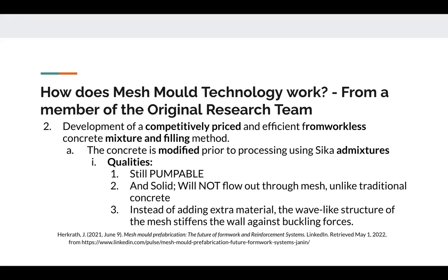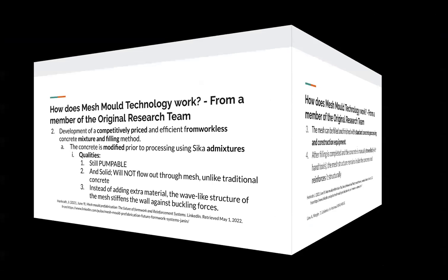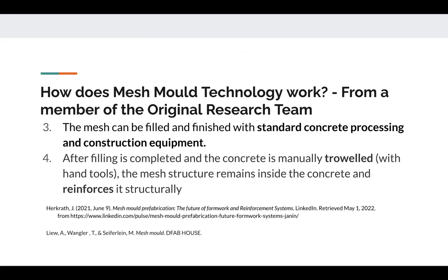And instead of adding extra material, like fibers, the wave-like structure of the mesh stiffens the wall against buckling forces. Number 3, the mesh can be filled and finished with standard concrete processing and construction equipment, which makes it easily reproducible. Number 4, after filling is completed and the concrete is manually troweled with hand tools, the mesh structure remains inside the concrete and reinforces it structurally.